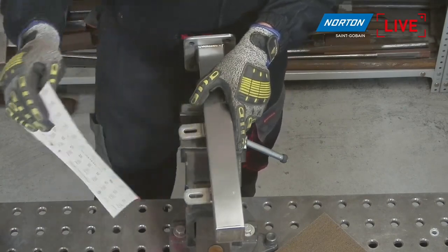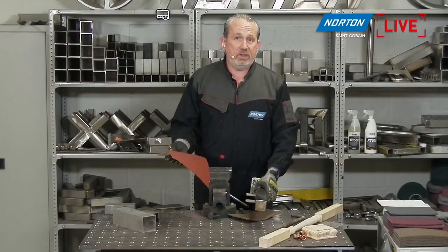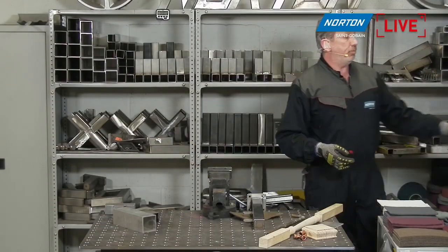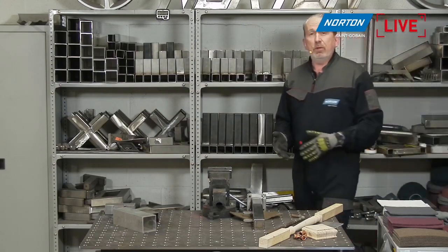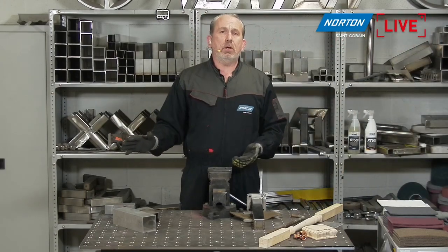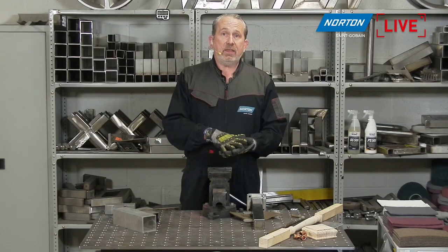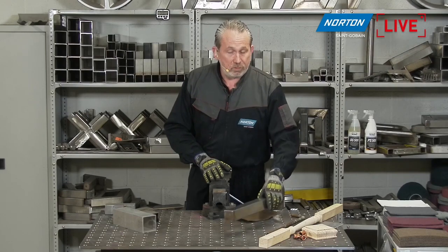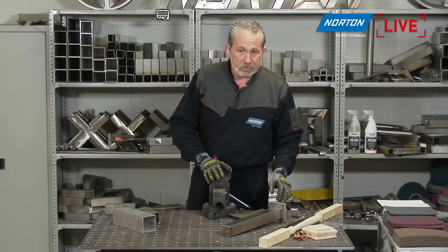With hand pads, because they spread the pressure of your hand over the full material surface, you don't see that as much. So in more particular applications like automotive, where they're painting cars, they're absolutely ideal for this, because after you've got a gloss on a car, you will see that damage in the body of a car if you don't use hand pads and use traditional papers.